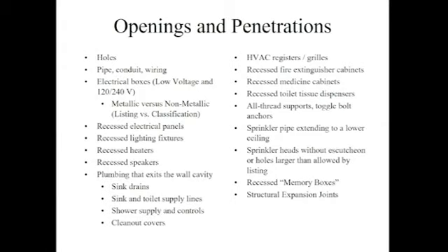And I haven't seen a rated one yet, especially the plastic ones from Lowe's or Home Depot or any other online kind of place. So you have to box out around it and continue the rating around it if you can, like on a bearing wall. When you get to a barrier, it may not be possible because there's no such thing as a 1 hour fire stopping assembly that just has one layer of chipboard behind it.